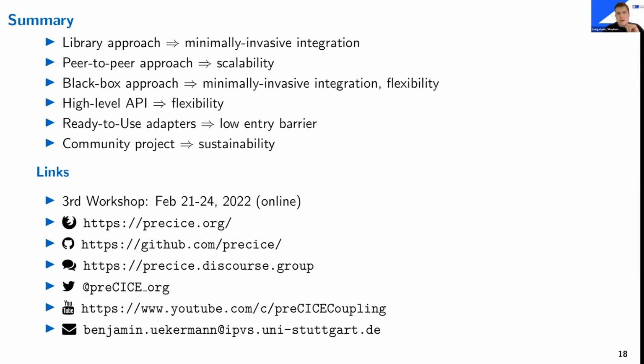Okay, thank you. And from Karim Ali: do the coupled softwares move in time similarly, or can we allow a solver to move with faster time steps, for example in CHT, where the timescales of the fluid part are much smaller than with the solid part? Yes, technically this is already possible now, that you can use different time step sizes, and then you couple only every fixed time window.